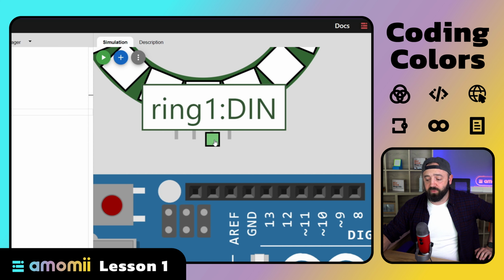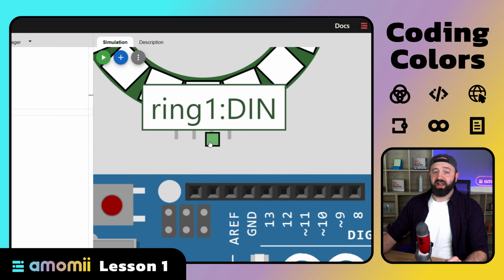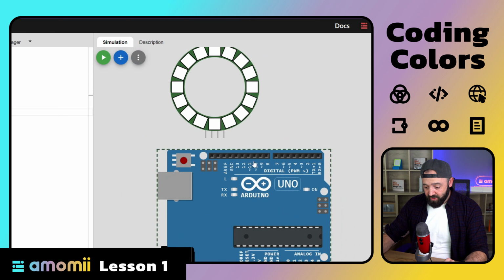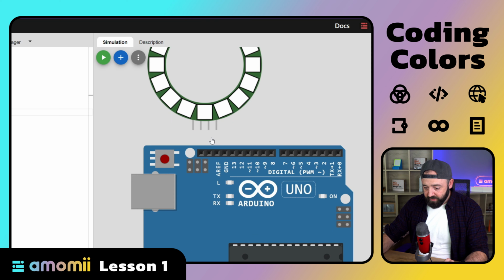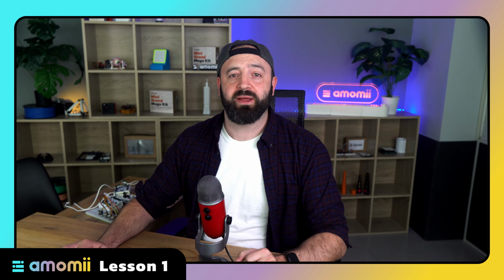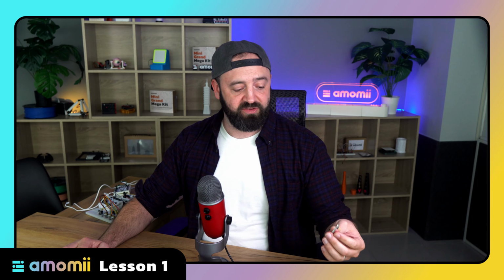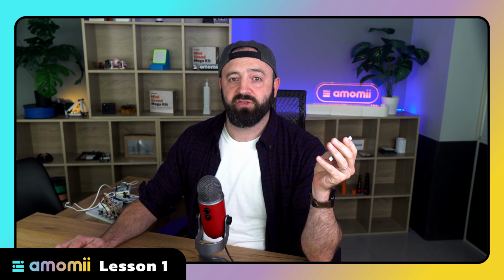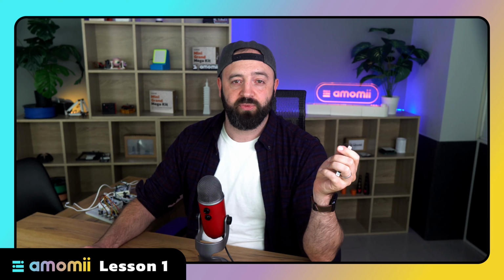The other pins are the ones that we'll be using. We'll start by looking at this one, DIN. Now, DIN stands for digital in. This is where we're going to receive information in from the Arduino. So the Arduino will send a signal out and it goes into the DIN pin of the ring here. So I'm going to connect this one to digital pin 9. You don't have to use digital pin 9, but that's just my go-to when I'm using pixels like this. I always use pin 9, so it's just logged in my memory that way. You don't have to use 9. You could choose 7, 6, 5, whatever else, doesn't matter.